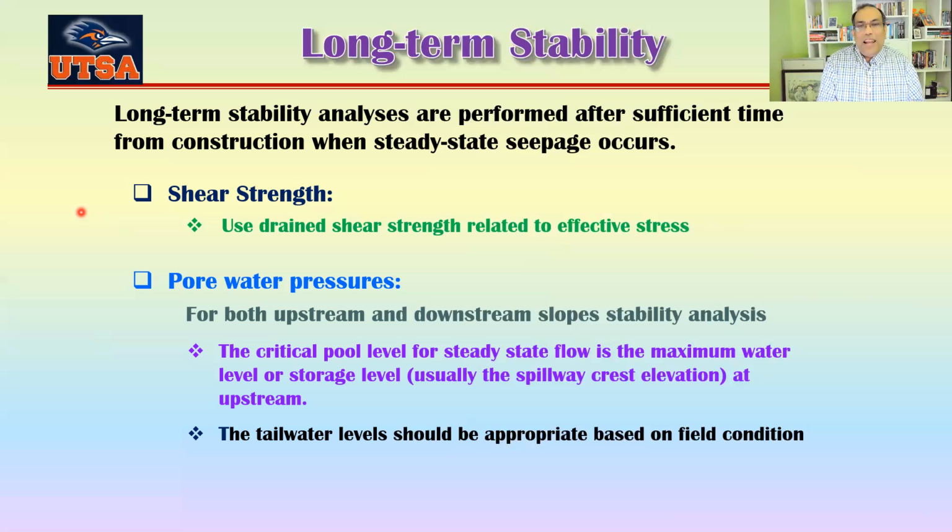But a dam is not like that. The dam always has a different level of water, okay? It's changing. In dry condition, this one goes a little down, and in rainy season, this one goes a little up, but this one will never be the same, okay? So that's basically the biggest difference, and it has a very important impact on the performance of the slope.